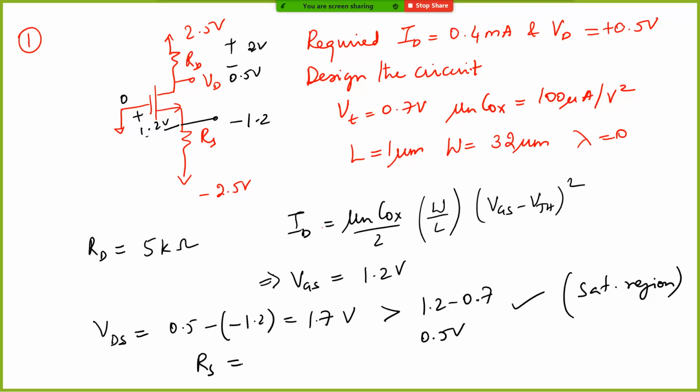Yeah. So one thing, since we are using the equation of the saturation region itself, then won't we be expecting? No, you will not. If we evaluate VDS. No, you will not, because in this equation VDS is not there, right? There is no VDS in this equation, right? So what you are saying is, if it is in the saturation region, okay, this needs a gate to source voltage of so much. That's all. The VDS is not included in this equation.